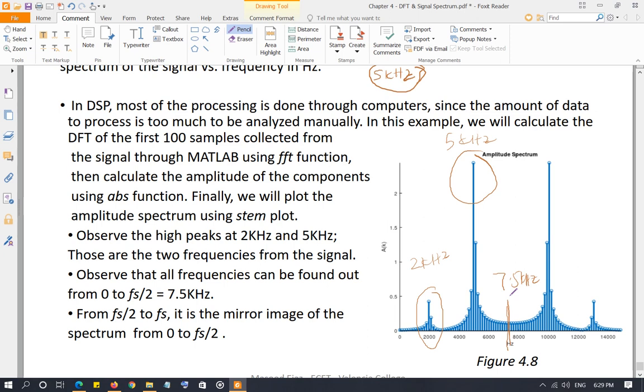Look at all these. This is what I was talking about, the spectral leakage or the noise if your signal is not properly cut, such that if you have a discontinuity when you repeat the signal, that's what's going to happen. Those are the harmonics. It's called spectral leakage, that we are going to discuss in the next topic, and that will be for next week.